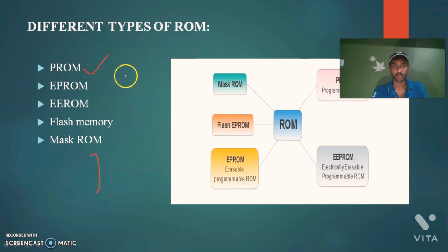So which diode is connected to the data line will produce an output. If I need to change that output, I just fuse that component, so that I disconnect the connection between the word line and the data line. So this is how a PROM can be manufactured using ROMs only. It allows users to write the data only once.